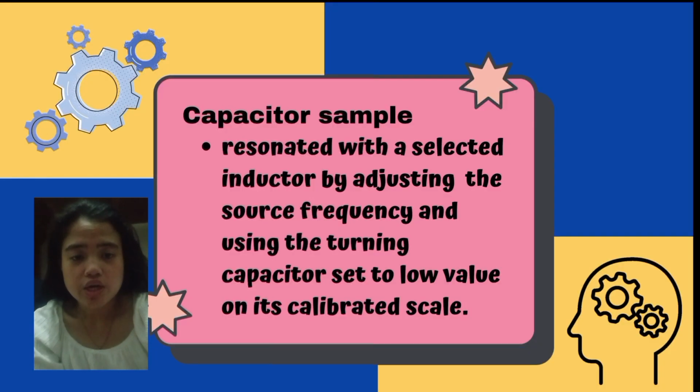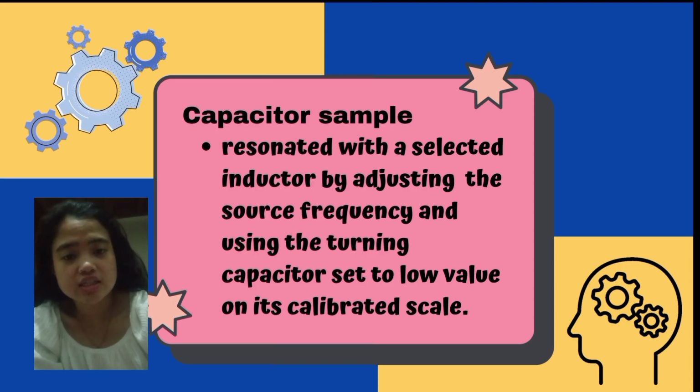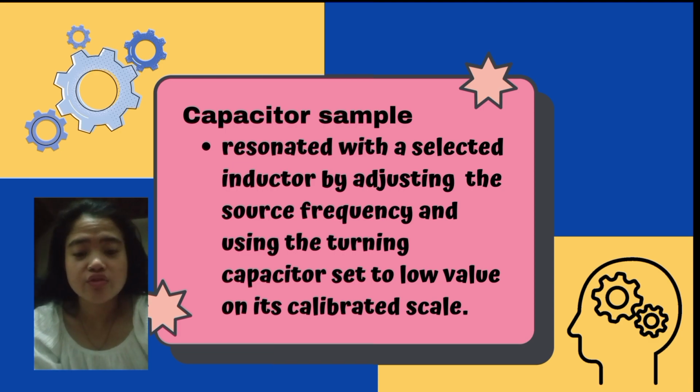A capacitor sample is resonated with a selected inductor by adjusting the source frequency and using the tuning capacitor set to a low value on its calibrated scale.